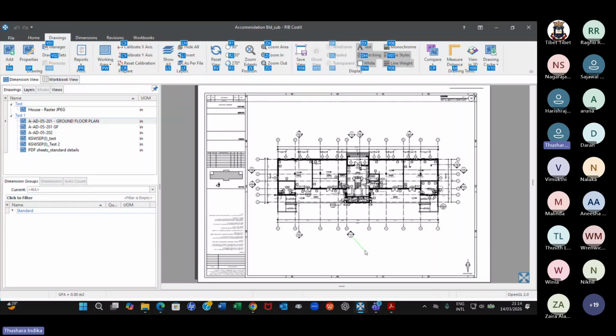And then since we are talking about rotation, you just type R1. It doesn't necessarily have to be lowercase or capital. You just put R1, you'll get 90-degree rotation. R2, 180, R3, 270. So you can try other functions as well, here ZI, ZO.